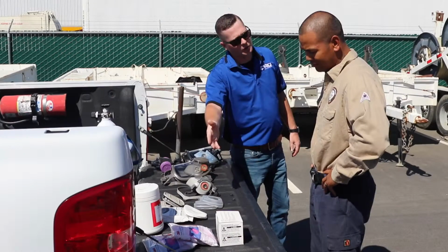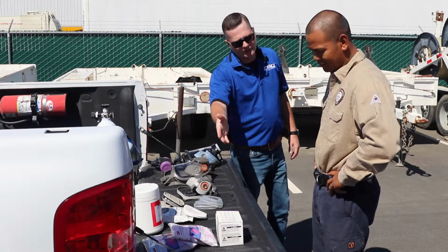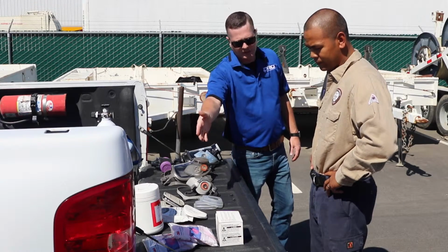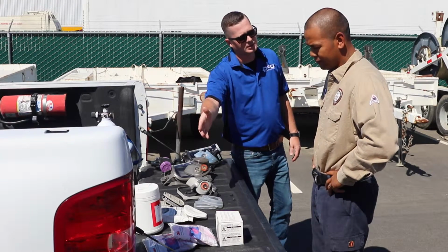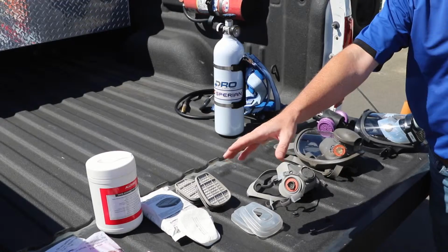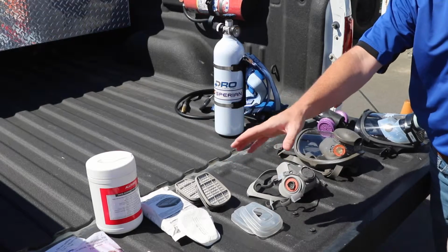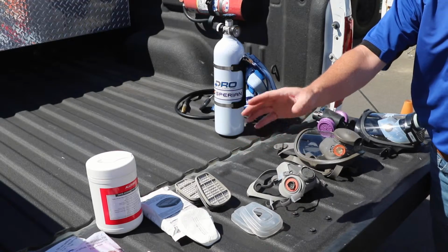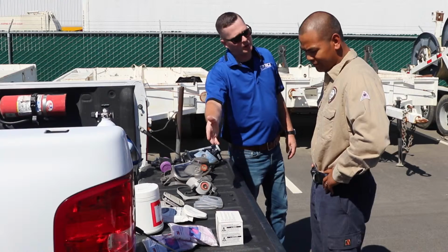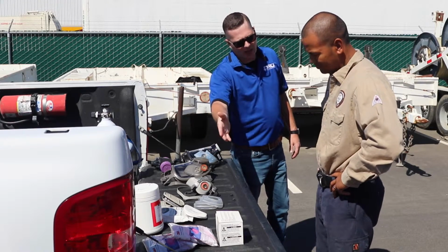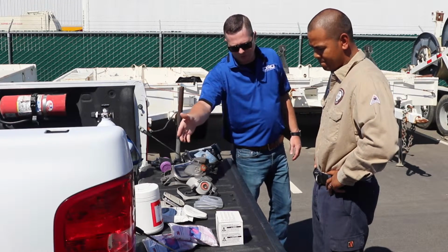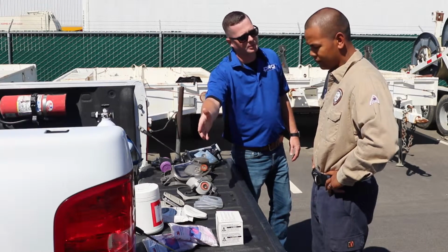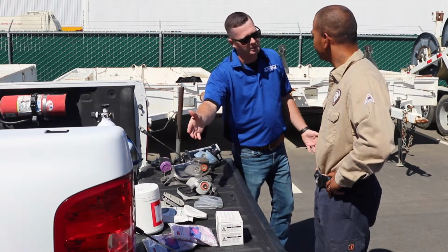Let's get started. It's extremely important to select the right respirator for the task. Selecting the appropriate respirator is based on the respiratory hazards to which you'll be exposed during the work being performed. You want to make sure it can be used in compliance with the conditions of its certification as well. It's important to evaluate the exposures and identify the contaminant's chemical state and physical form to make sure the correct respirator is selected. When evaluating the respiratory hazards, make sure to get the right people involved.